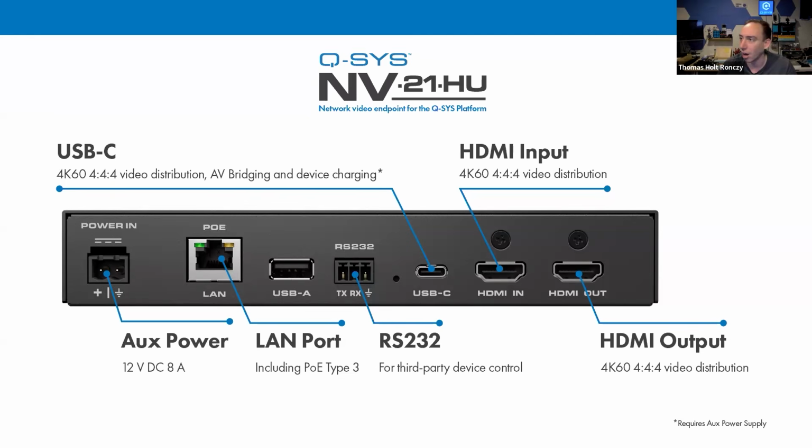that connection. And then William asked why the power supply voltages for the NV21 and the NV32 are different. The reason for that, William, is that the NV21 is meant to be a super small form factor. So bringing that in at the 48 volts of the NV32 would require us to have a step down transformer inside of the box, which would make the NV21 much larger. So we opted to bring it in at 12 volt, where the step down requirements are a lot smaller. We can use smaller step downs and deliver voltage where it needs to be, with a lot less footprint.